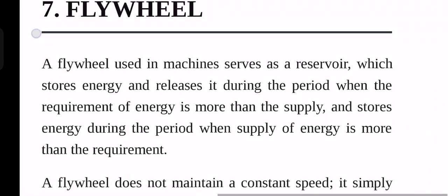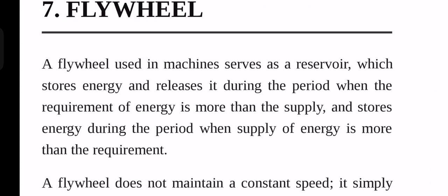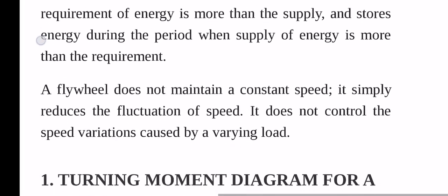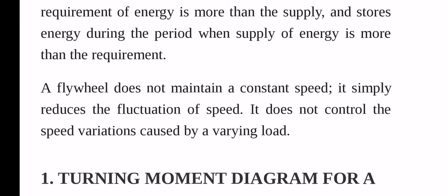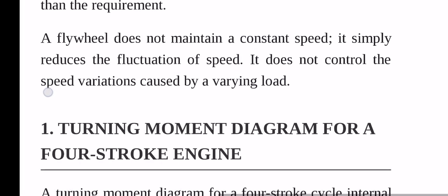Flywheel. A flywheel used in machines serves as a reservoir which stores energy and releases it during the period when the requirement of energy is more than the supply, and stores energy during the period when supply of energy is more than the requirement. A flywheel does not maintain a constant speed, it simply reduces the fluctuation of speed. It does not control the speed variation caused by varying loads.